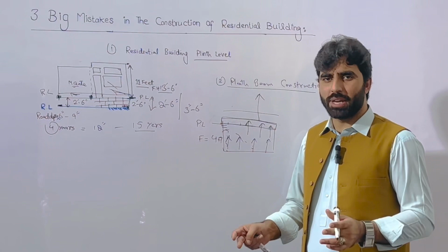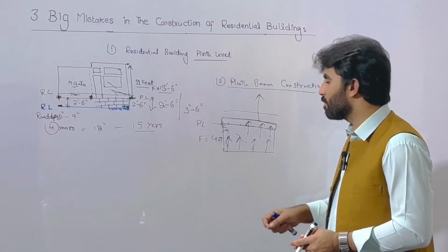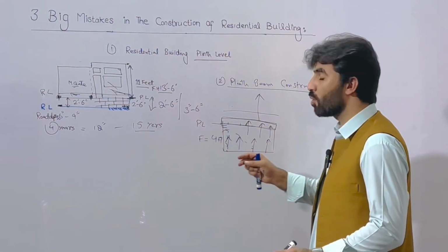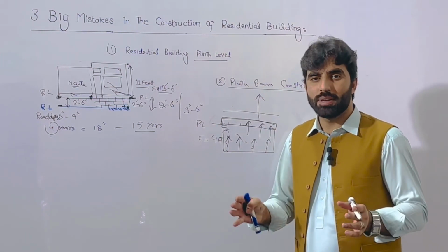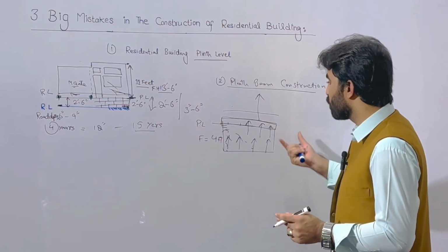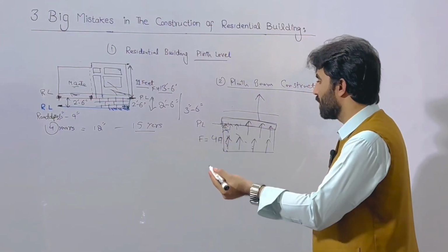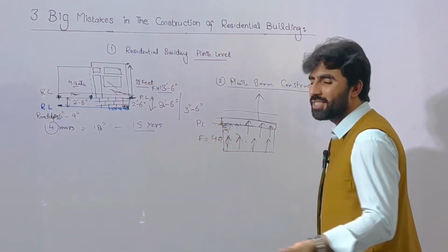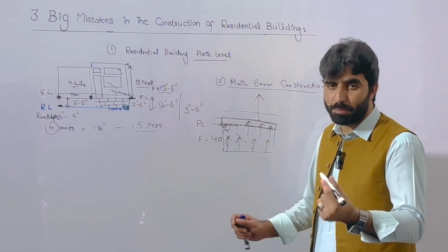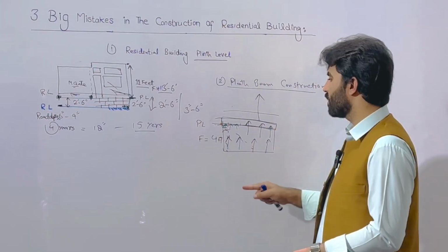We have a lot of methods to remove the seepage from the house, but that is very expensive for you people. So therefore the plinth beam is very important to make a good bond between column and beam. That is a kind of monolithic building, so therefore it becomes strong. Seepage can't go easily inside the concrete, but in brick masonry it is very easy. On the top of the plinth level you can provide a polythene sheet or plastic, which is a kind of waterproofing. So therefore this is very important.